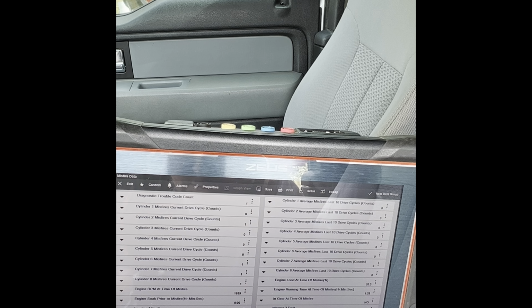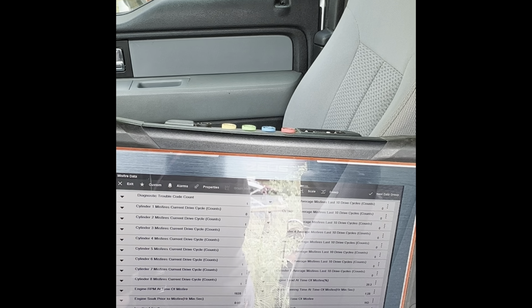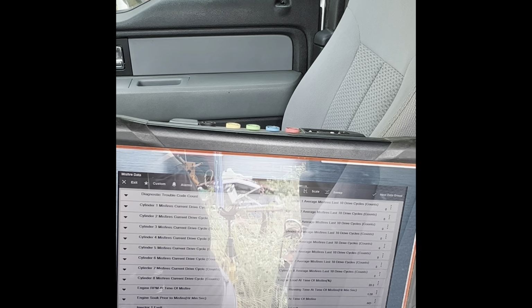We got 2, 6, 7, and 8. They're not bad misfires, so we'll just pull them and see what they look like.